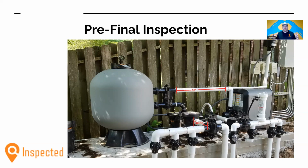It needs to be straight so that the water can flow in a laminar fashion. This is very important because if you're using a 3-inch pipe, you're probably using a larger pump. And those pumps can be up to 2.5 feet long. And you add that another foot of pipe in front of it. If you're trying to stick that in a 5-foot easement from the fence to the house, you are running out of feet to put the rest of your equipment in. So plan your equipment pads accordingly.